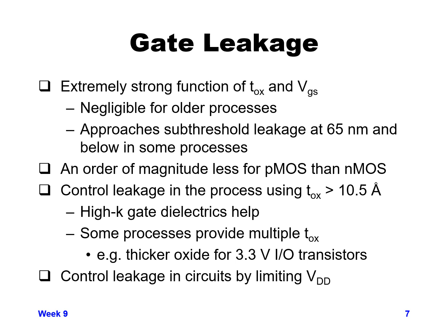One of the comments that I will make is that for a while the PMOS actually had an order of magnitude less leakage than NMOS. I'm not going to go into the physical reasons for that. And as the oxide thicknesses got smaller and smaller, eventually we had to go to high K gate dielectrics in order to remove a lot of the leakage that was going through the oxide, and that actually has helped the gate leakage a lot.